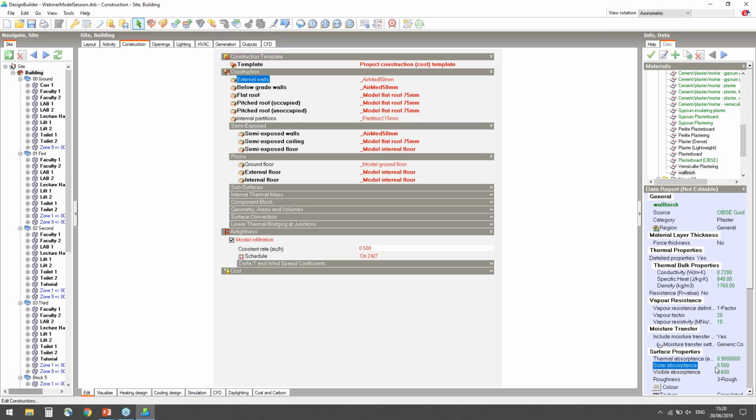You should create user-defined materials in the model when you are using scripts and changing their properties. The reason for this is that unlike normal modeling, where you cannot edit logged library data, the script will allow you to change it. So if you use your own custom items, then it avoids unintended messing up of DesignBuilder library items.